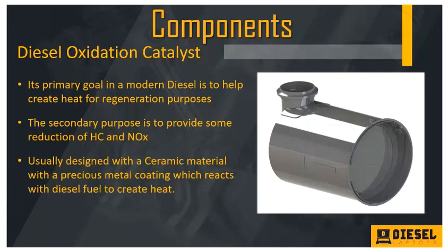purposes. Now, these DOCs are usually designed with a ceramic material, which has a precious metal coating, which reacts with diesel fuel to create heat. I wanted you to hear that it's usually designed with a ceramic material with a precious metal coating. Here's why I'm telling you this.